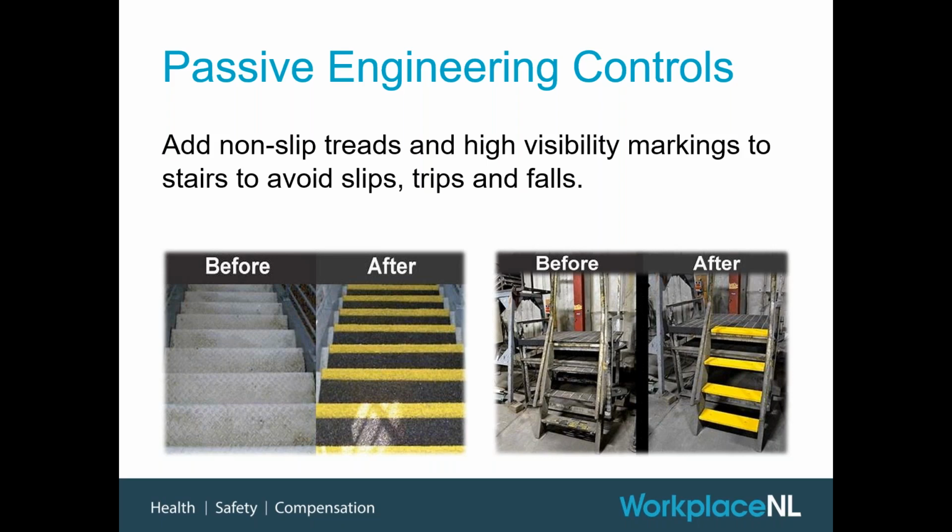You can also add high-vis to the edges, especially important if you've got any irregular stairs, so stairs that are not really built to the current code. These are, again, little minor things you can do to reduce slips, trips, and falls.